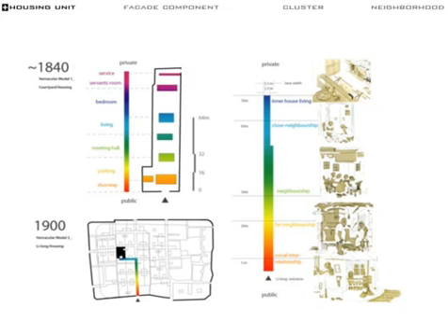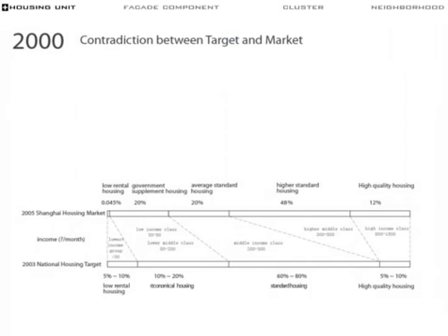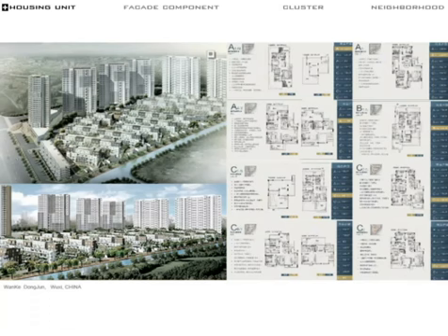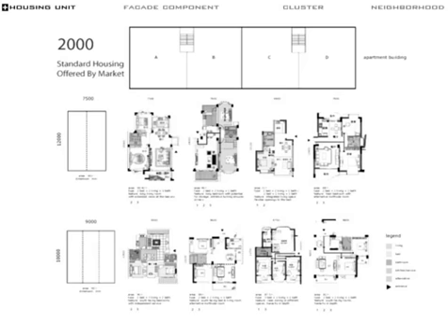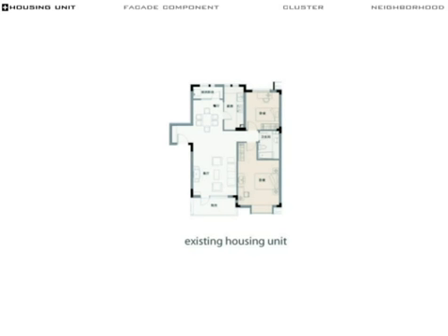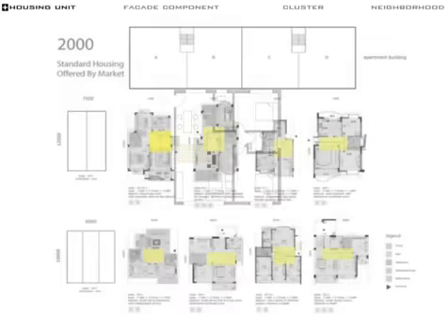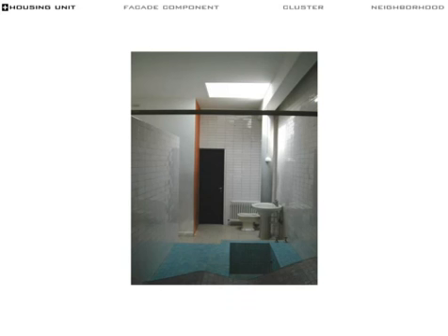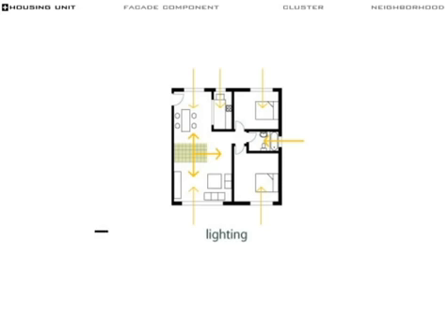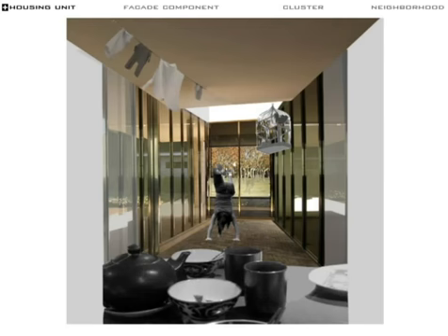The intention of this project is to learn from the spatial organization of the vernacular models, aiming at exploring a possible model of modern Chinese living quality and offering an alternative strategy for middle-income people. The current housing market delivers an effective typology following a sophisticated logic of room arrangements. The analysis of 90 square meter standard plans suggests the potential in the core living area where a void space can emerge. A private skywell performs better for lighting and ventilation. More importantly, its spatial quality creates a modern way of Chinese living.